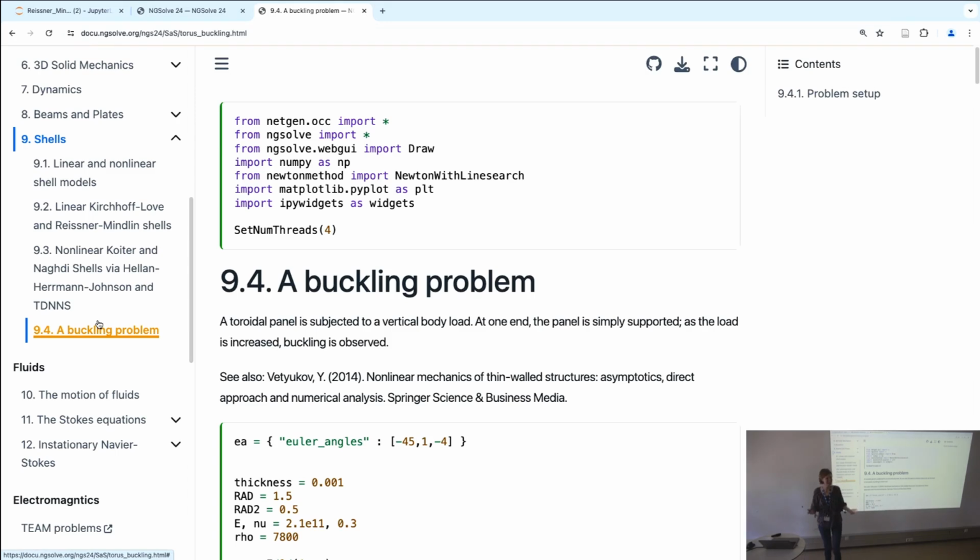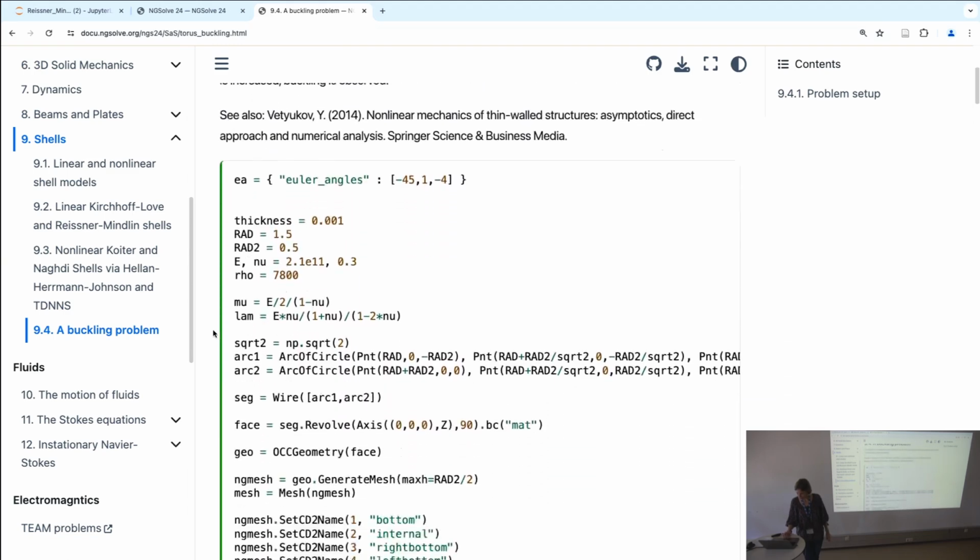So just from an engineering point of view, those shells are really unbelievable. When I saw them first, Michael in Linz showed us this example with rolling up the beam, and it was going, I think, 7 rounds with 10 elements, and that's not standard. Also, I don't know how many shell elements you know that work on triangles and quadrilaterals in the same mesh at arbitrary order and at perfect accuracy.